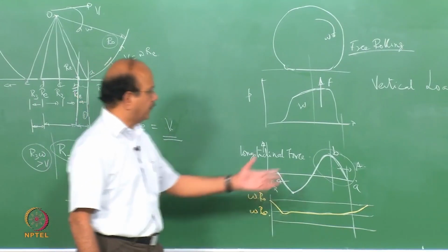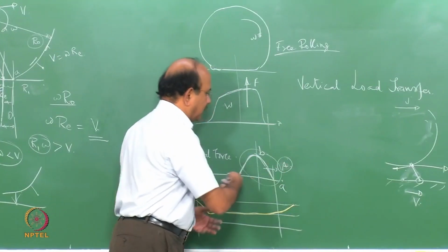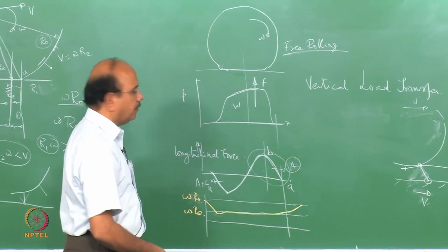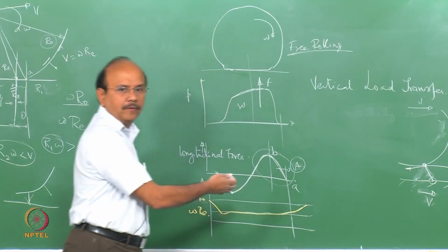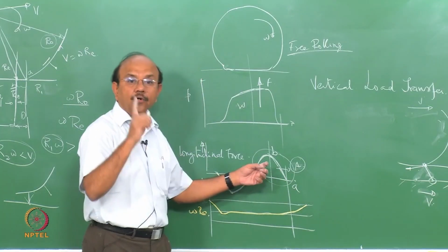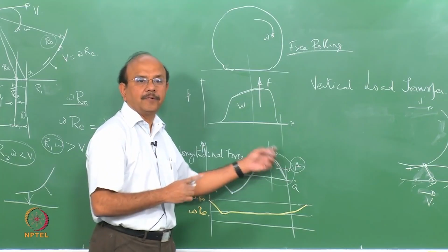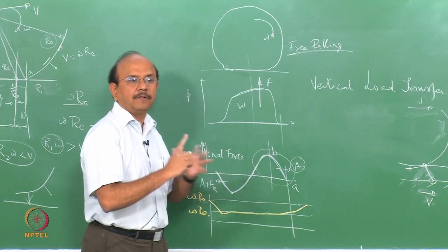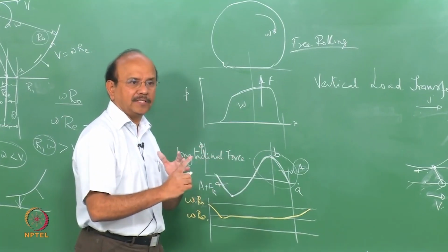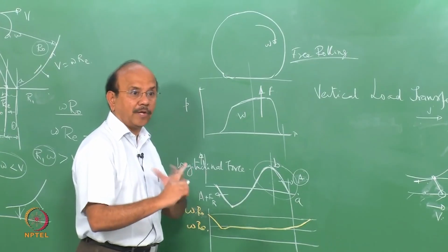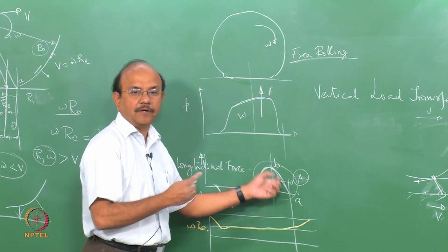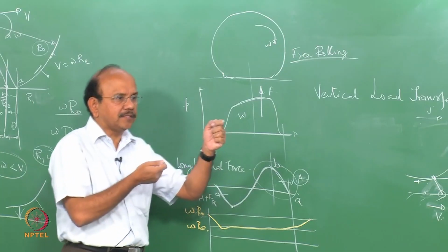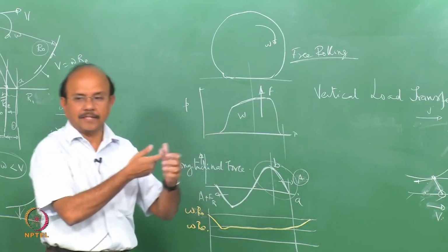So if the total force that's acting is A, please remember there's compression and tension, the curves are different, so they are not the same, and all those viscoelastic concepts now come into the picture here. Because after all, the tread is getting compressed and relaxed, compressed and relaxed, and so on.